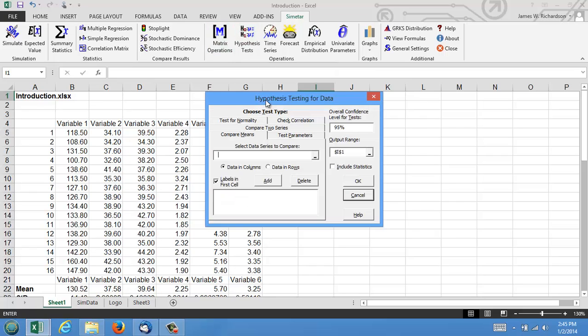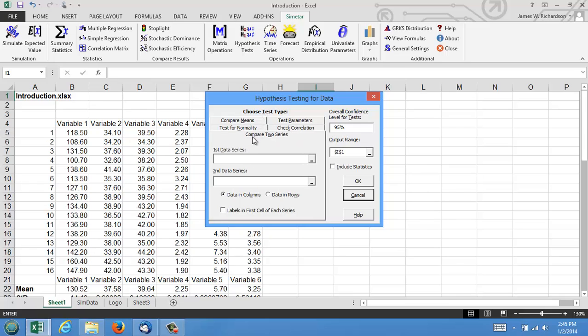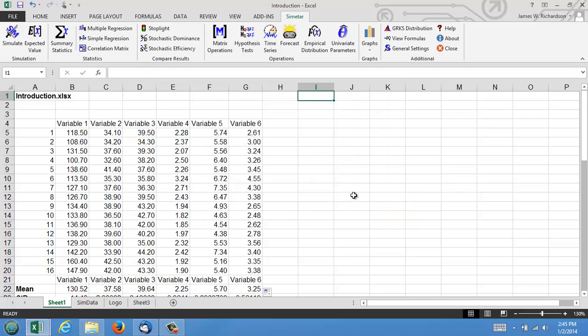Hypothesis testing is one thing that is frequently ignored in simulation models, and so we have made it specific into our package here. If we generate a set of random values, we might want to test those against the historical values to see if we reproduce the mean and standard deviation of the original data. If you're working with a multivariate distribution, you would highlight multiple columns of data here and their corresponding simulated data here, and click OK, and it would do 3 different global statistical tests to determine if you reproduce the vector of means and the covariance matrix.